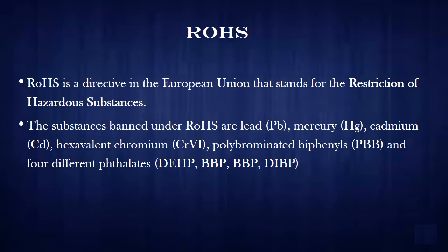Next certification is RoHS certification. RoHS is directive in the European Union that stands for the restriction of hazardous substances. The substances banned under RoHS are lead, mercury, cadmium, hexavalent chromium, polybrominated diphenyls, and 4 different phthalates.